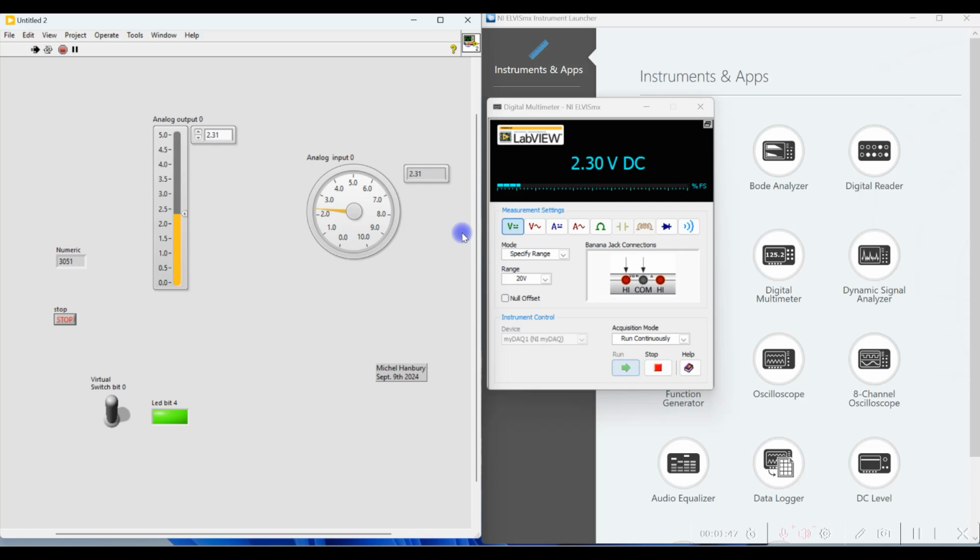The next thing I want to show you is I'm going to move a jumper wire here from the analog signal to the digital signal. I have a little opening in my wire that I can connect the test lead to. And you'll see here that it's measuring, previously I said that a logic high is 3.3 volts on the myDAQ because it's low voltage TTL. So the switch is high, measuring 3.2. So it's outputting 3.2 and measuring 3.3. If I bring it down, it goes to 0, back up, it goes to 3.3.